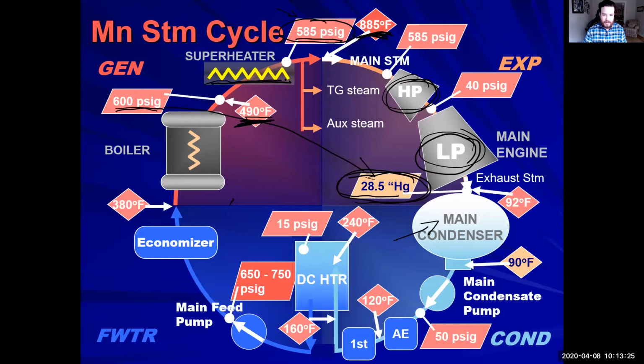When we go through this superheater, one, in the boiler, there is a baffle that does not allow moisture droplets that are entrapped in the vapor to go through. And I know we talked about this steam. This superheated steam is invisible because it lacks water molecules entrapped in it. All right, so that's something to keep in mind of what's happening. These are at high temperatures and high pressures because of what's happening inside the superheater.